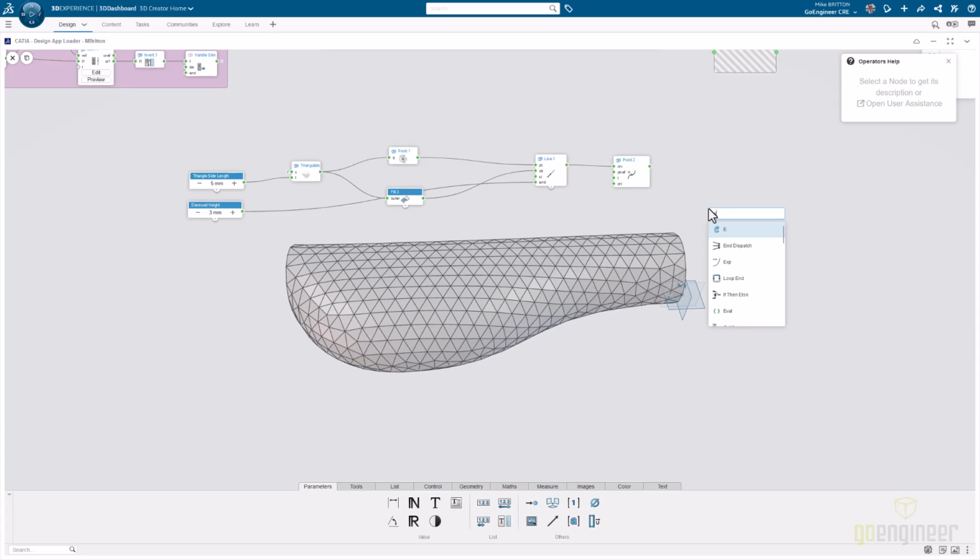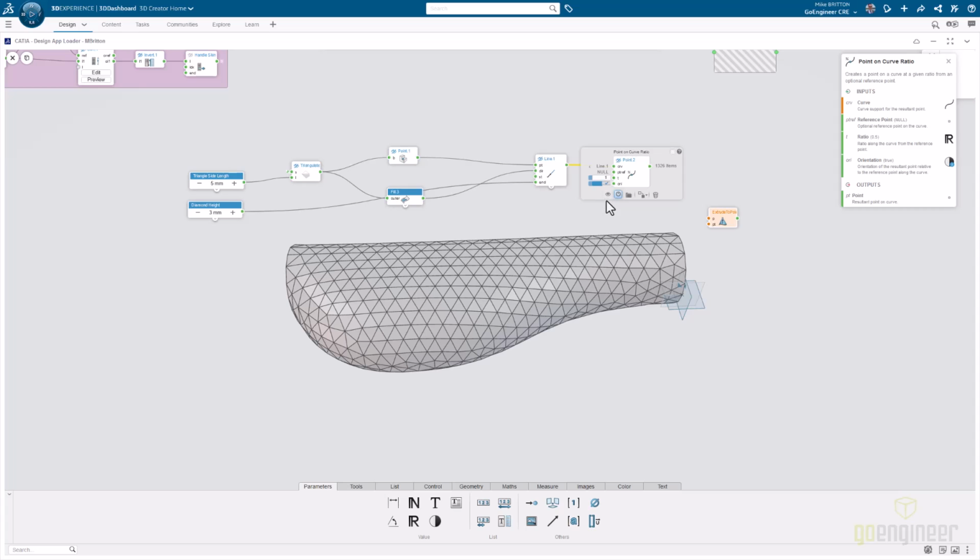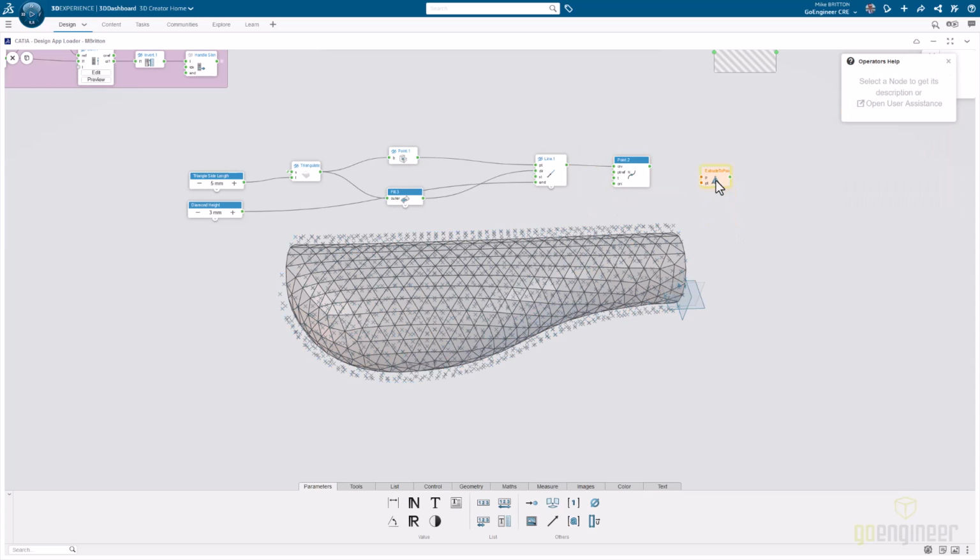The next thing I'm going to do is use the extrude to point command. So I went through all that hassle of creating those endpoints out there. If I left click inside of extrude to point, it's looking for our base profiles, and it is looking for the target point to which we are going to extrude all of those.